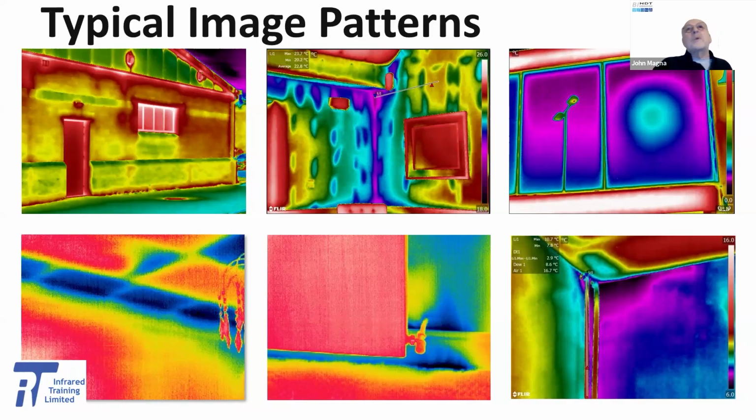So top left image, we can see cold or thermal bridging, missing and or inconsistent insulation and air leakage. Top middle image, we can see externally open convective loops, or as it's now referred to, thermal bypass behind the plasterboard that's been installed on dots and dabs of adhesive. In this case, this is where external air has entered the void created between the plasterboard and unsealed blockwork, cooling the surface of the plasterboard and exiting externally. In other words, it's not through air leakage.